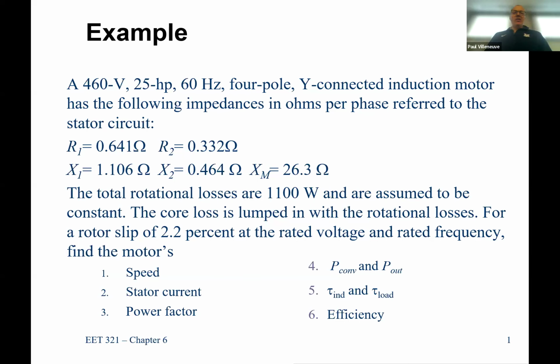Okay, let's get started. So last class, we did the equivalent circuit model of our induction machine, which is a rotating transformer. If you recall, our equivalent circuit now has the value of s, which is a way of introducing frequency. But we also wanted to reflect impedances, resistors, inductors, to the quote unquote high side or the stationary side of the AC machine.